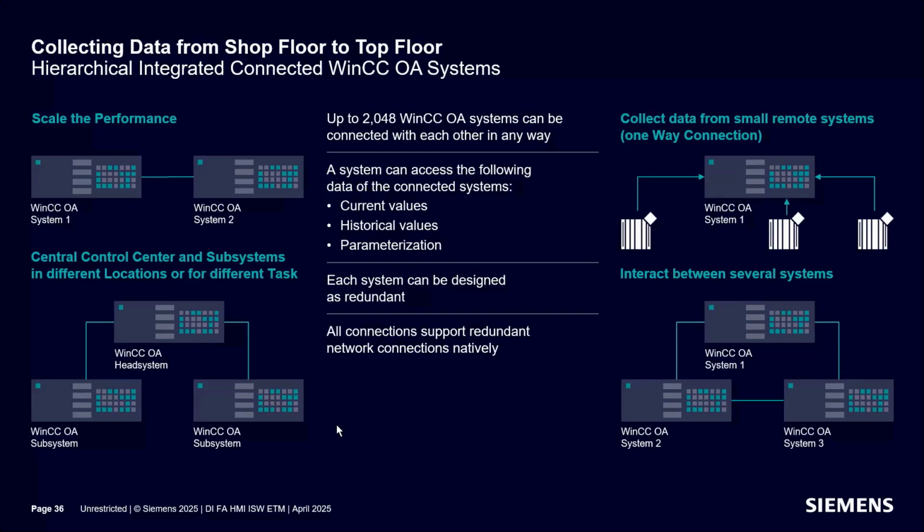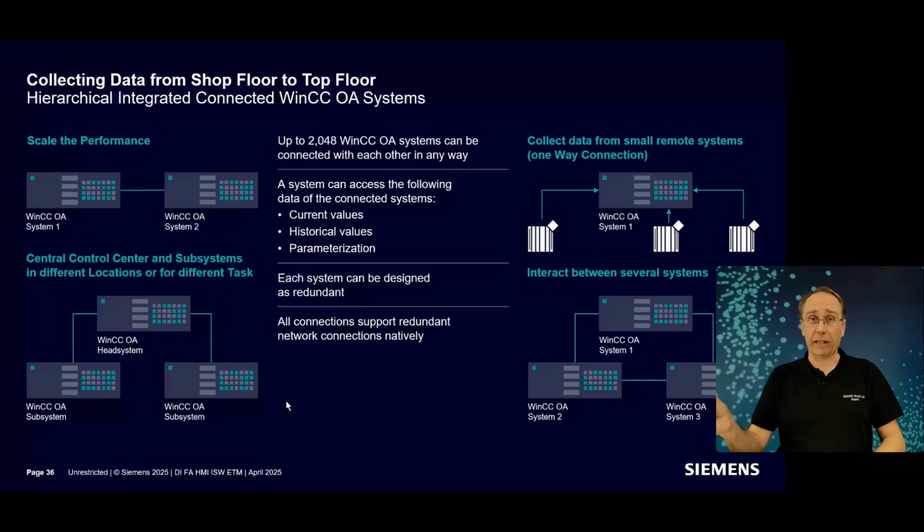So when you only monitor alarms, you can have millions of tags, and this is not an exaggeration, on one machine, as long as they don't change too often, because that is the limiting factor: value changes per second for a certain hardware type. And if you run into a limit, then you use 2 or 3 or 4 or many more. The limit is 2048.